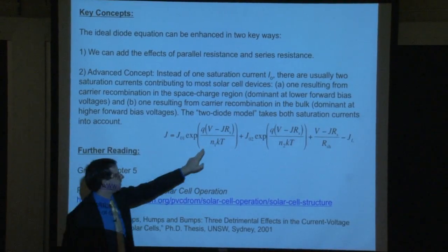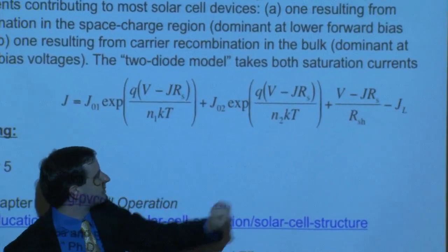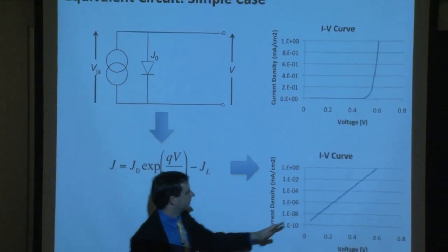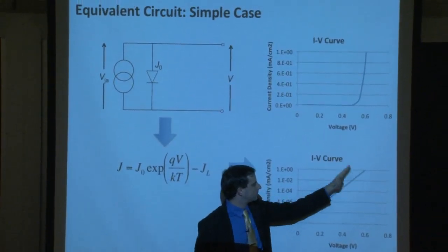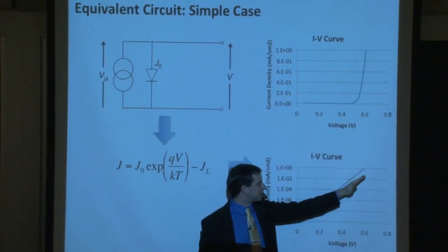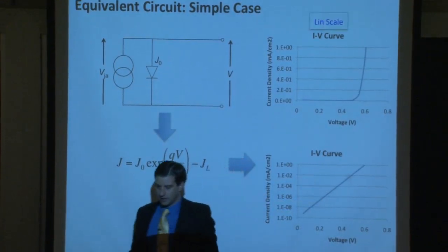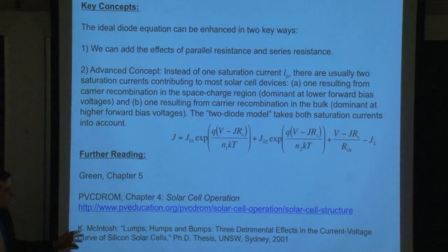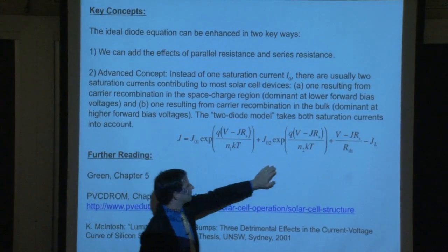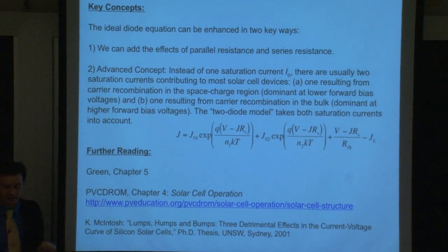Another thing you might see pop up is this ideality factor showing up right down here. The ideality factor is a slope factor. What that means is, if we go back to this, if you change your ideality factor, you're changing the slope in log scale. It'd still be a straight line, but if your ideality factor increases, you would get something like this. If it decreases, the slope would increase, right? Because you have the equation dependent on 1 over this parameter. Okay. So the ideality factor is important as well because it indicates the type of recombination mechanism that's driving the current inside of that region of the device.